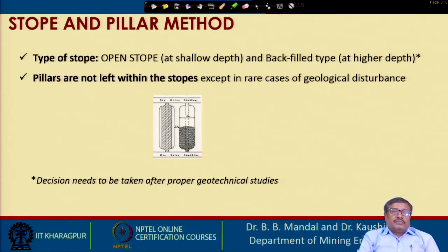That means, if you leave that particular stope after working, then what happens? It collapses. Okay. But if you want to avoid that, and when you know that when one part of the mine collapses, it can affect the other parts also, because the entire rock mass around the workplace will try to adjust itself to settle under the different kinds of forces acting on it.